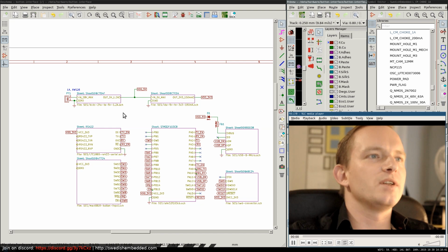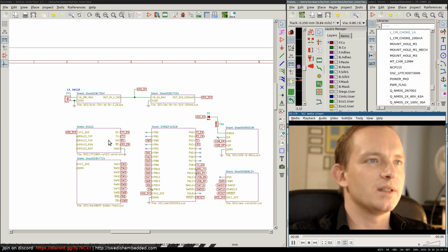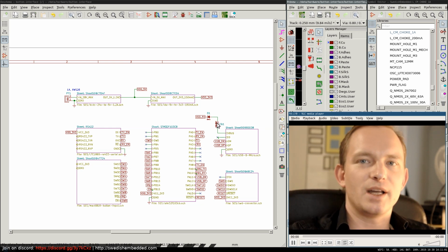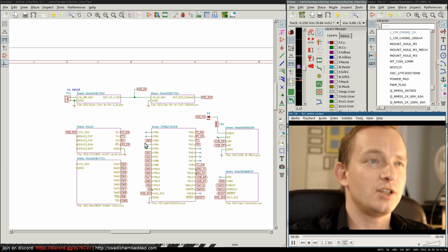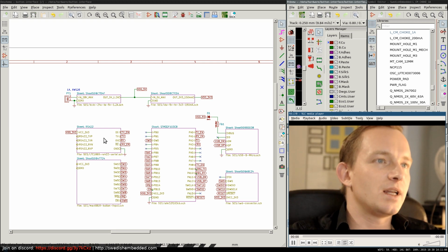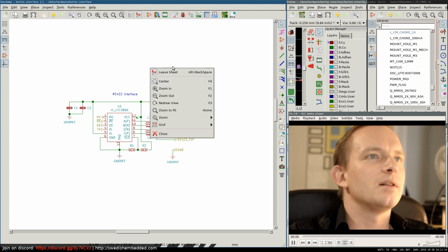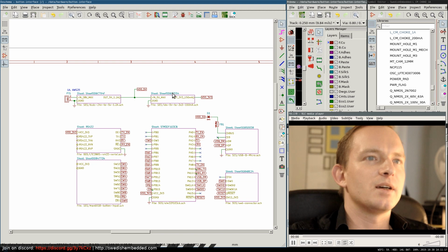And this has proven to be a little bit hard in KiCad because KiCad doesn't seem to have that kind of workflow in mind. So, for example, I can have the sheets in a sub-repository in the same directory where I have my project. But when I re-annotate the schematic, then all the annotations of the subsheets change instead of having all the annotations in the top-level directory. So that's a bit annoying, but it seems to work for now. So I'll just leave it like this, and we'll see if I can figure out a better way to do it as I work through this schematic.